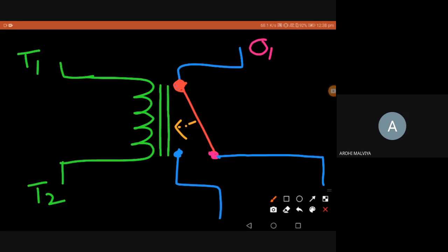So there are two output terminals and this is the input terminal: output one, output two. You can see the difference between the previous relay and this one. Previously it was just a disconnected relay. Now this relay is always connected to O1, and based on the energization from the input signal, it will be connected to O1 or to O2. This is one option. Another option is that more terminals are also possible. For example, I can have one relay like this.